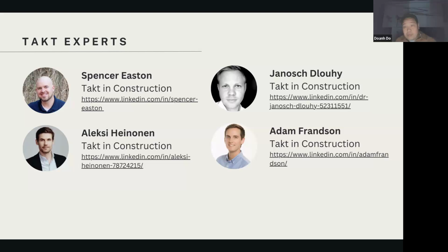Okay, I have here from Heather: good clarification, it's okay to start with a 5-day TAKT and work towards a 3-day and 1-day, start small and gradually. Yes, if it's your first time doing TAKT, the easiest thing to do is a 5-day TAKT, because you have your weekends or buffers. A 3-day TAKT is an intermediate level, and a 1-day TAKT is very hard, because if you mess up, it causes a lot of problems. So I would not go to 1-day TAKT right away. I would start with 5 days and work yourself up. Okay, anyone else have questions?